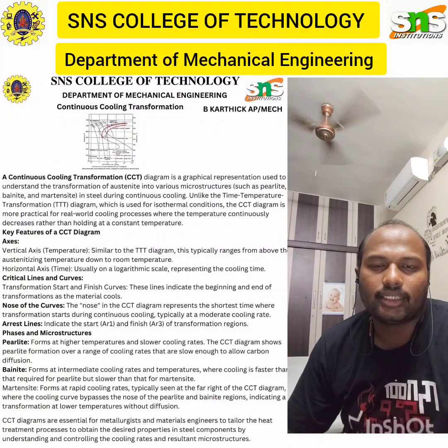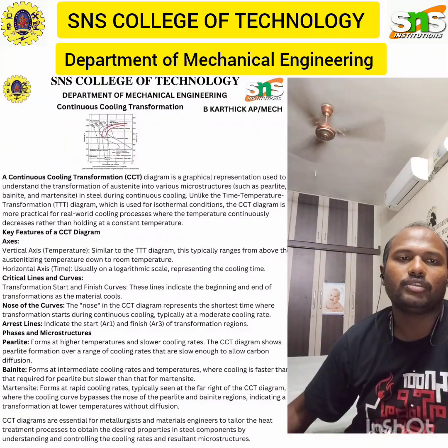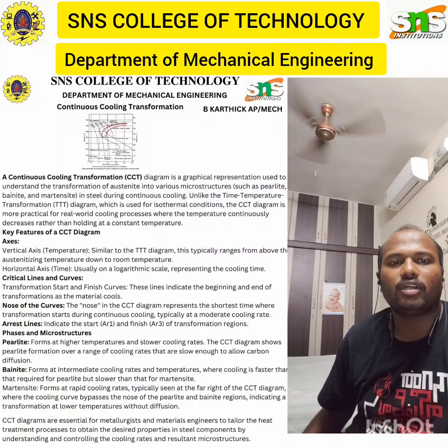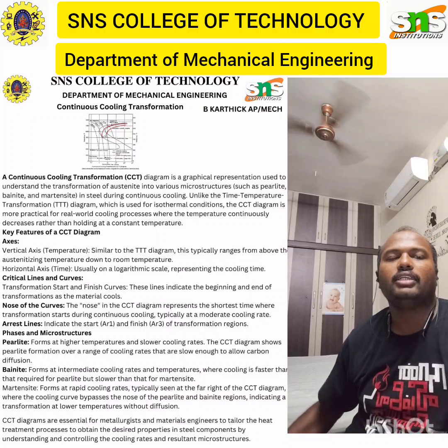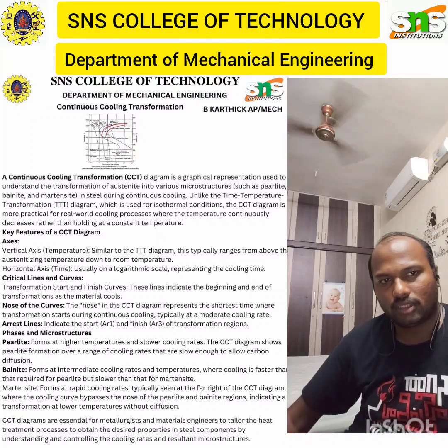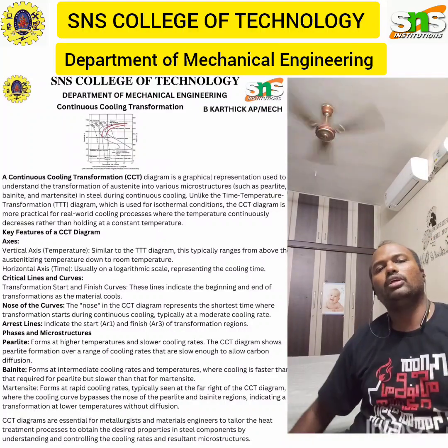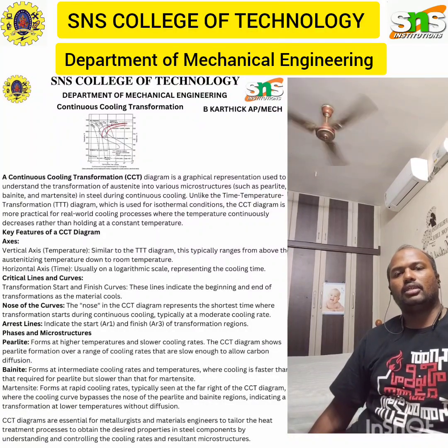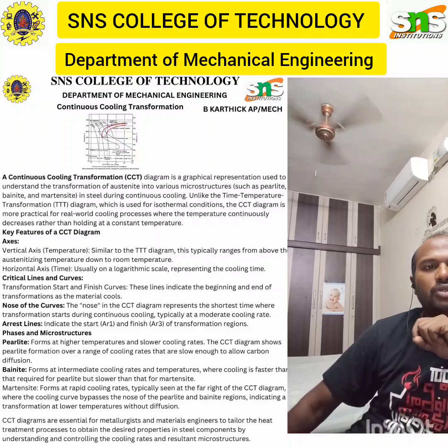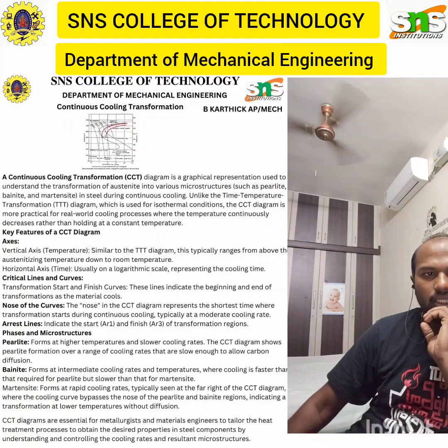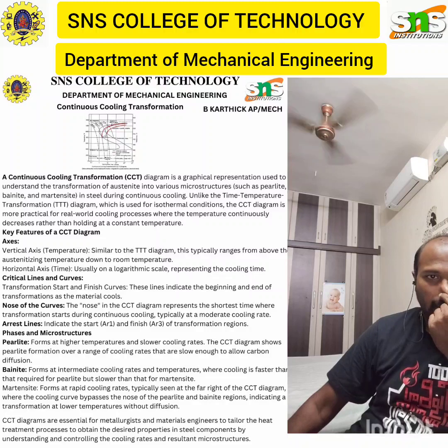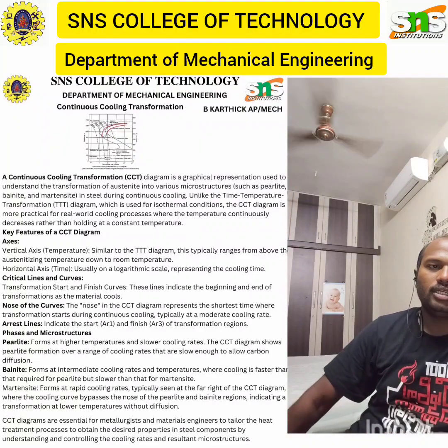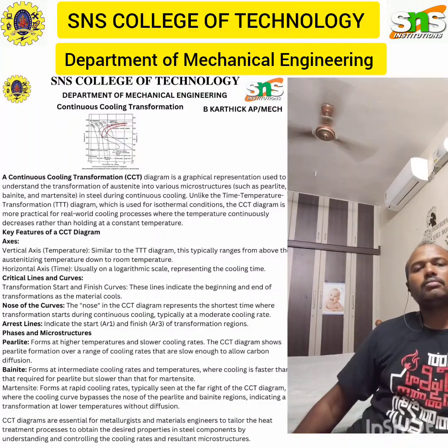So unlike the time temperature transformation, that is the TTT diagram, which is used in the isothermal condition, the CCT is more practical for real world cooling processes, where the temperature continuously decreases rather than holding on to a constant temperature. In the CCT diagram, the vertical axis is temperature, similar to the TTT diagram. This typically ranges from above austenite temperature down to room temperature. In the horizontal axis, usually a logarithmic scale represents the cooling time.